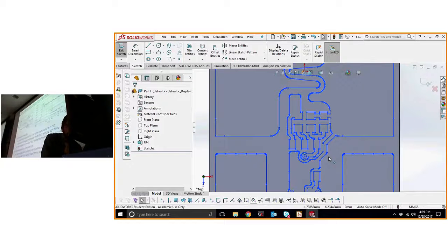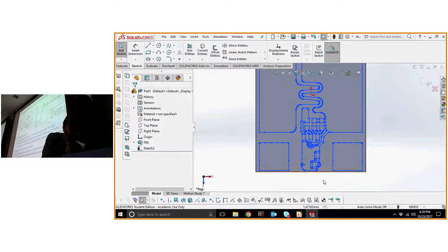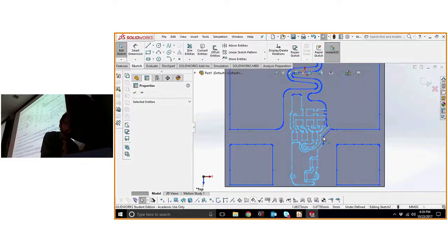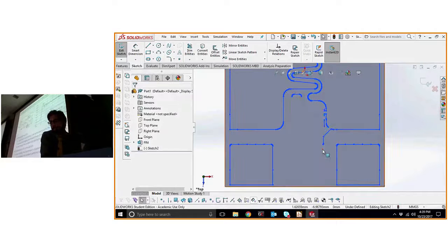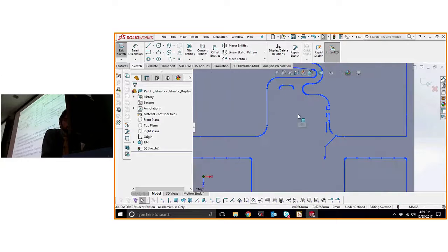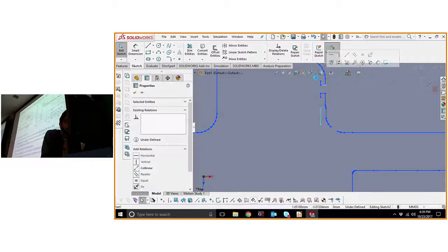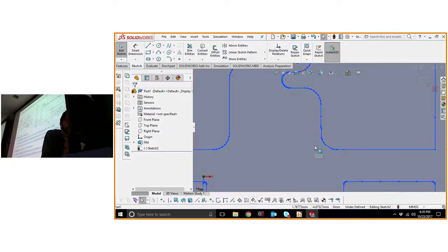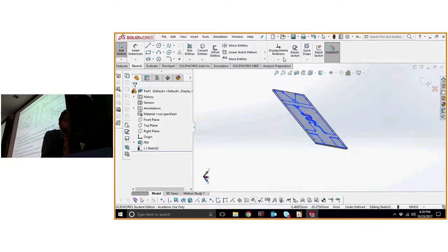All the copper, but this mess isn't that great. Like, we don't really care about that. In this case, that's all the driving circuitry. Maybe at some point that would be something you're interested in, but it'll just complicate the simulation. So I'm going to go ahead and clear all that stuff out since I'm only concerned with the commutation loop. And just join this remaining segment. Great. So those are our top copper.